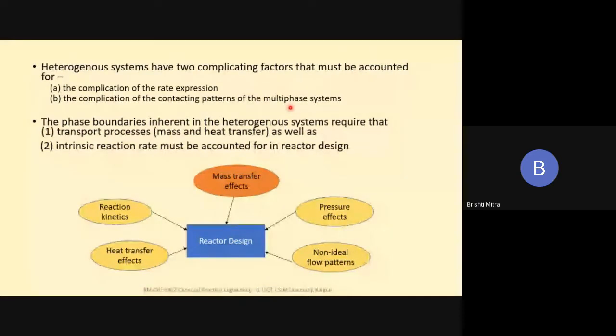Apart from that, when we're talking about multiple phases, the contacting patterns of these phases become important. Just like if you have an absorber, unless there's a very good interfacial area and contact between the gas and the liquid, the mass transfer will not take place. And unless mass transfer takes place, your absorption process will not happen.